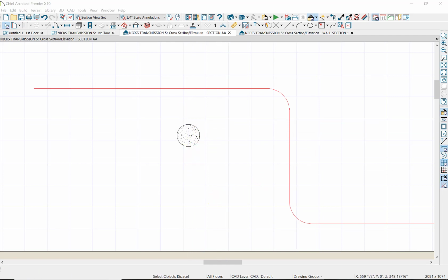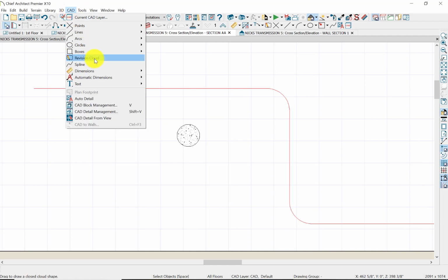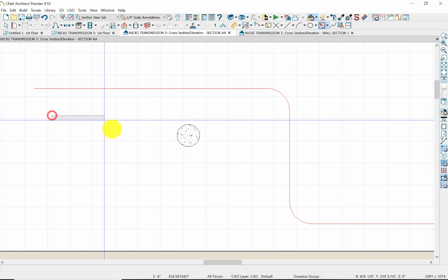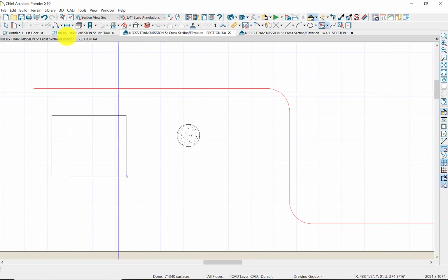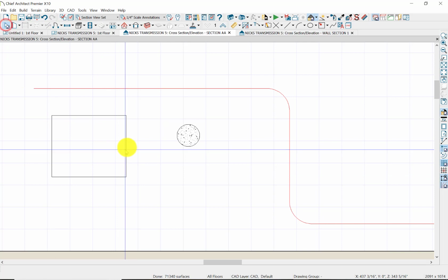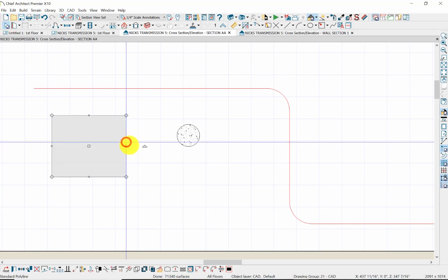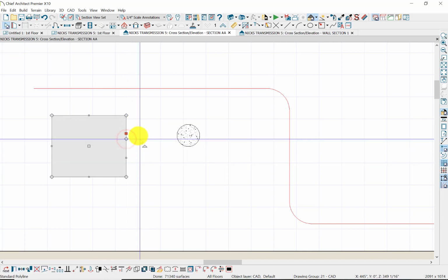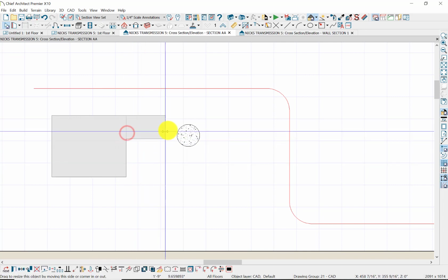All right, let's talk about the rectangular polyline. There it is. Very useful for all sorts of things. Because with the rectangular polyline, we can break it, use our break tool, and you will be using this tool left and right once you get the hang of it.